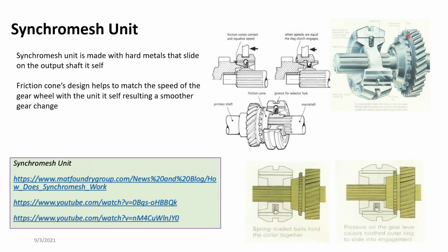So that's what actually happens in these gears. This system is very simple, but everything depends on the quality of these components. Since these two are rubbing against each other during operation, this is actually made of brass, so it's known as a brass cone. When the gearboxes get older, this part starts to wear out very easily.